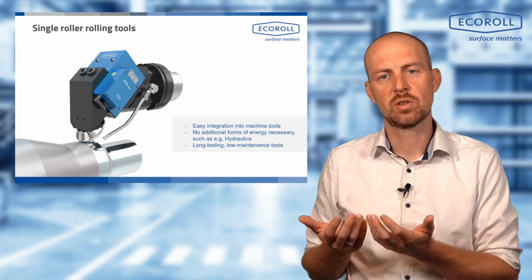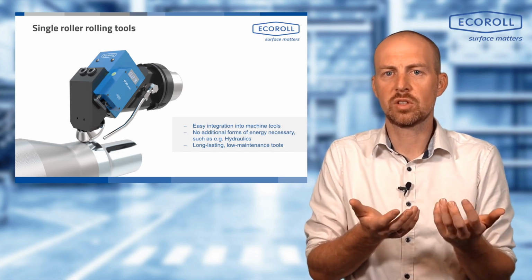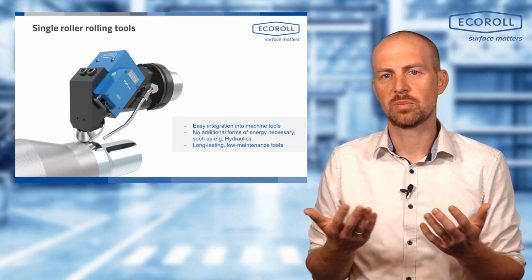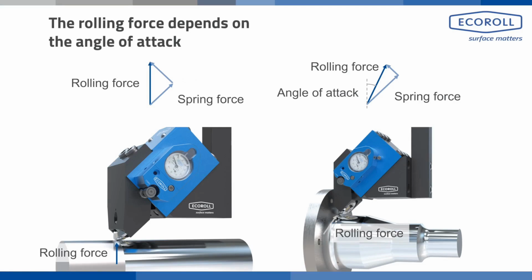Both the analog and digital measuring gauges actually only measure the deflection of the leaf spring and then transfer this either analog or digitally into a force value. This force value is of course calibrated. It is predetermined, but we have a spring characteristic that correlates this spring travel with the rolling force. If we want to control the rolling force in the process, we must of course consider the angle of force application. The whole thing is of course somewhat exaggerated at this point. The rolling force is not that sensitive. I just need to ensure that it has the right value at the right place.